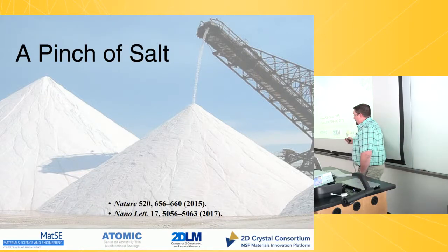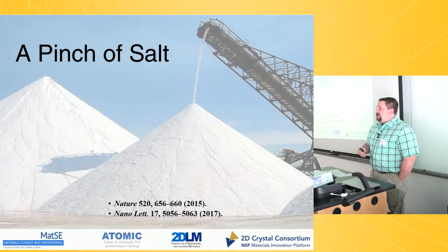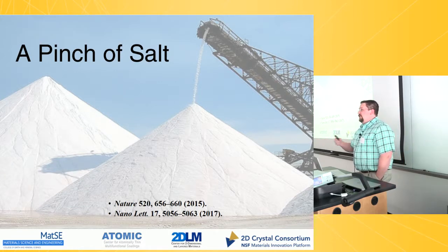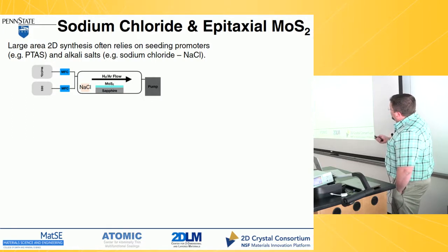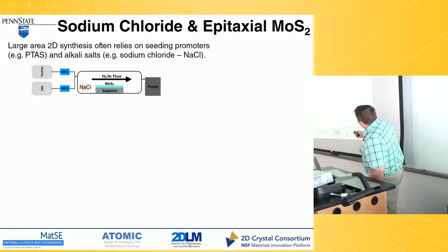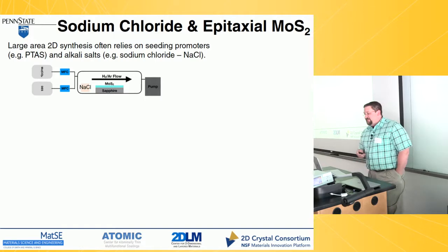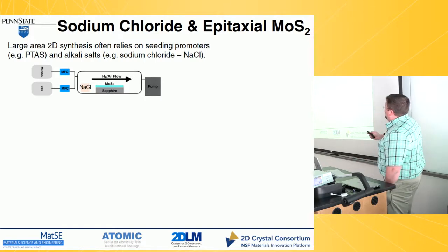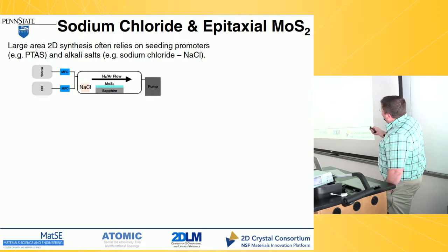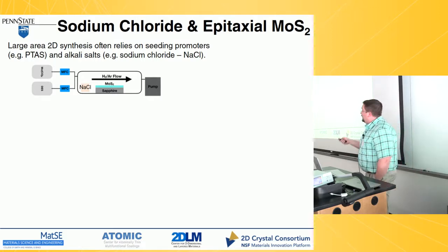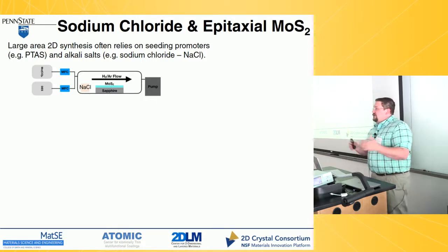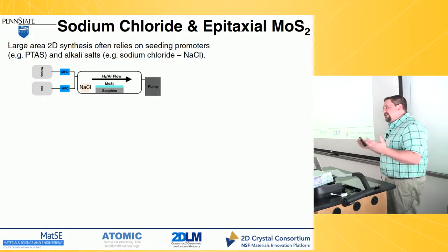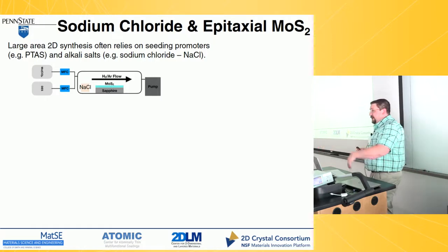And then there was another paper that just more recently came out that just further pushed this effort of using salt. So we looked into it, MOCVD, dimethyl sulfide and molybdenum hexacarbonyl. Apparently I needed my coffee after my lunch. And we stuck some salt in there up the furnace. Now clearly you can change the position of the salt, so you can change the amount of salt, sodium chloride, et cetera, you put in there. You can do the same thing with potassium iodide.